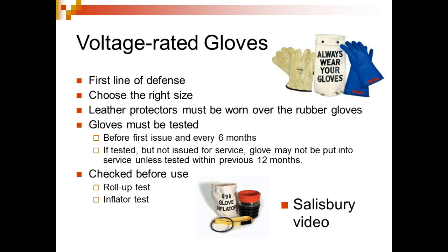So some of y'all might have a true RMS meter, but if you're working on variable speed drives or pulse width modulation and stuff like that, you probably need a true RMS meter. If you're working on just standard AC circuits, then a standard meter will work fine, right? All you got to do is pay attention to your maximum ranges and also the category of the voltages you're going to get into.